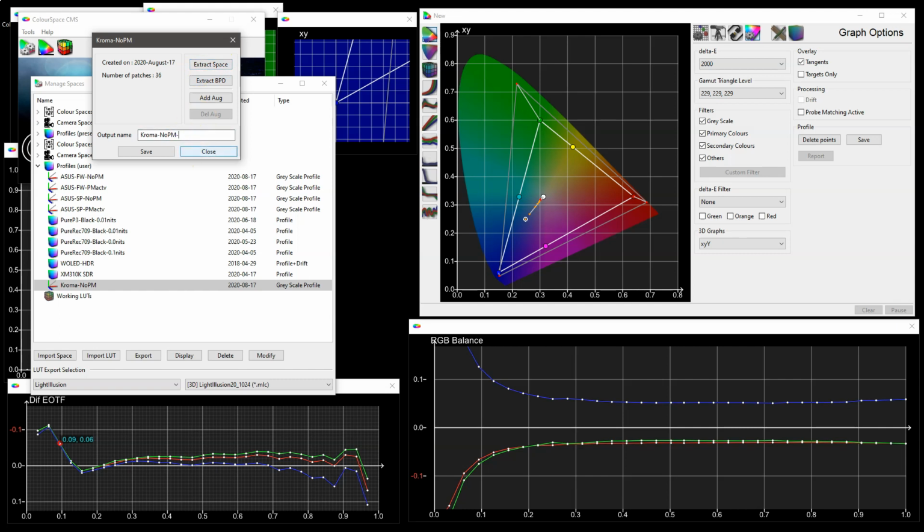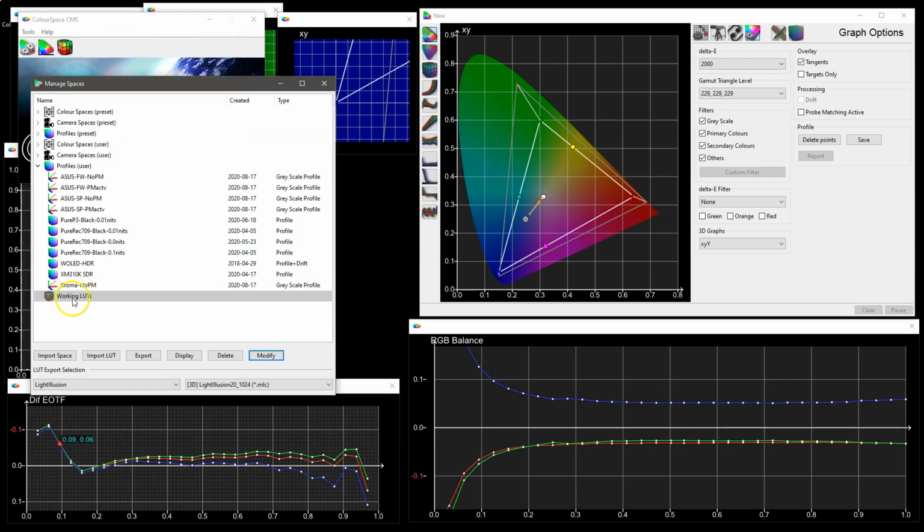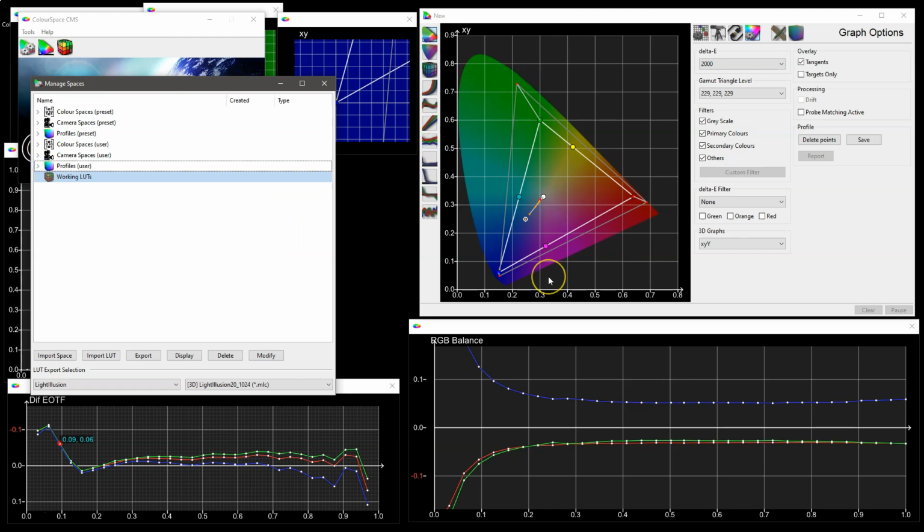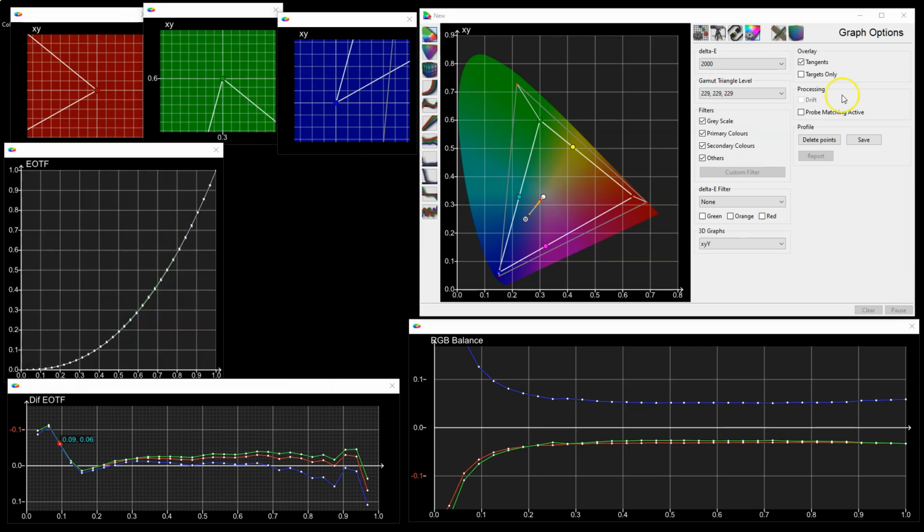So we will just add onto this extract, or EXTR, and say extract space. Now this will try and get an average for the gamut and gamma EOTF of the display. So it ain't going to be 100% because we've only got 3 color points with the grayscale, and it will be close, but it won't be absolutely perfect. But it will be perfect for what we need it for. So again, just get rid of that.